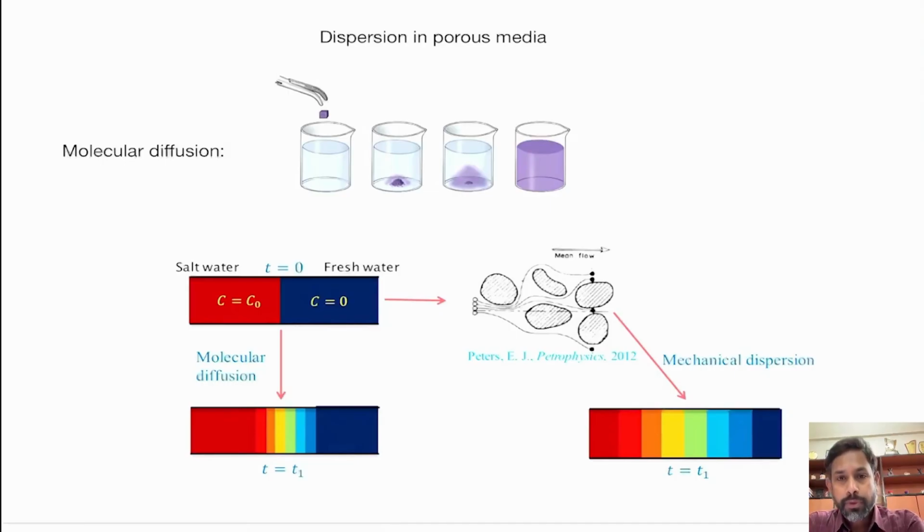So far, in porous media flows, we have seen different basics of the flow, including Darcy's law, continuity equation, and solute transport equation in porous media. We also understood what is porosity and how it is defined or calculated in porous media, permeability, hydraulic conductivity, etc. They are all basics which you need to understand flows in porous media.